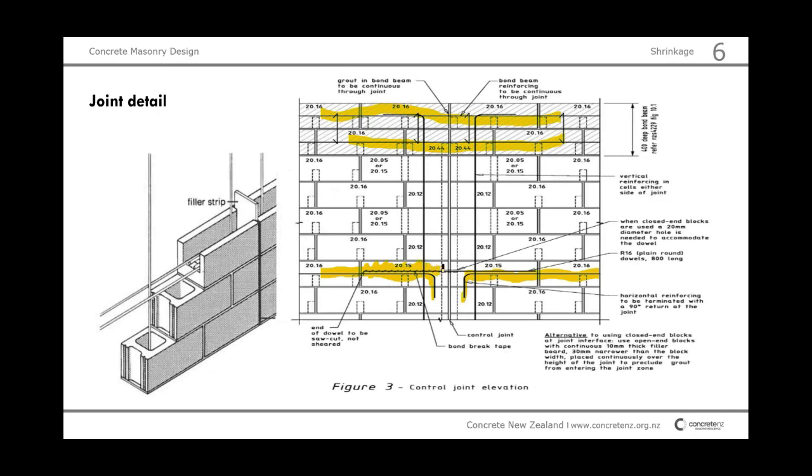of that lap bar, and then there's the other bit sitting in the concrete. You see the vertical reinforcement just here in the last cell of the block, and that will tie in and lap in then as well into the bond beam.